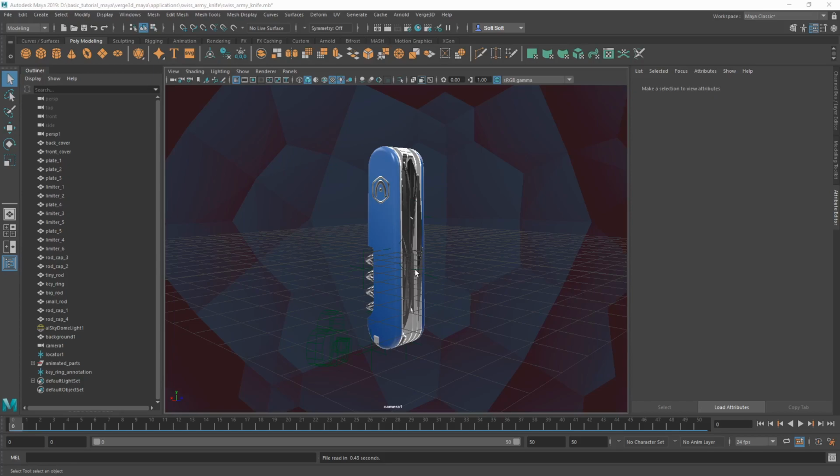Of course, this is only applicable to meshes that are not animated or somehow used in the scenario as separate objects. So you can safely join such meshes and improve the rendering performance as a result.